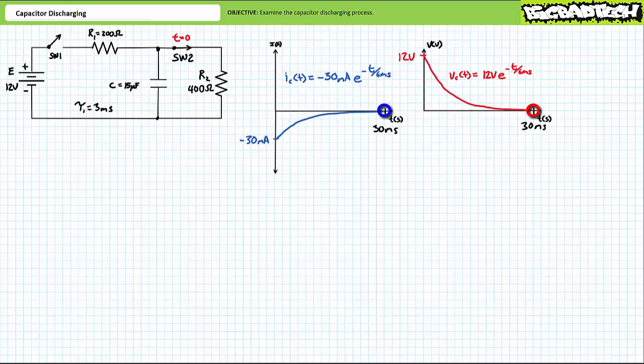You'll note discharge current ceases at the same time voltage across the capacitor drops to 0 volts. It makes sense. Given no voltage differential, there exists no charge and no incentive for current to continue traveling. The capacitor is discharged and we enter a steady state at-rest condition where all stored energy in the capacitor has been dissipated by the resistor in the form of heat.